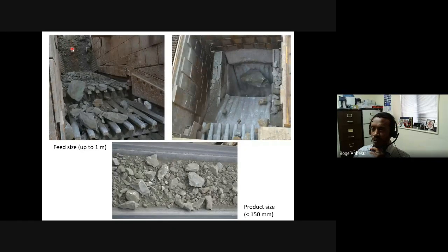As you can see, there are lots of fine particles and also some large particles. This large amount of fine particles shouldn't be sent to a jaw crusher, because there's no point in feeding fine particles to it. It's designed to handle only large rocks. If you feed fine particles to a jaw crusher, you just end up limiting its capacity.